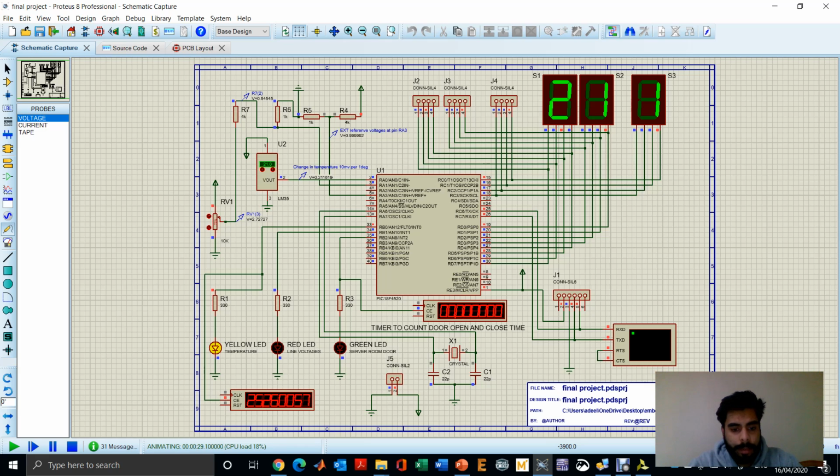So we can see the first time when you turn it on, it takes 25 seconds and the temperature will appear here. Once the temperature is more than 20 degrees, the LED will be on, because it will potentially cool down the server room. Imagine the air conditioning system is on, and now the temperature is below 20 degrees. It will take the average, and we can see it's now 19 degrees and the LED is off.